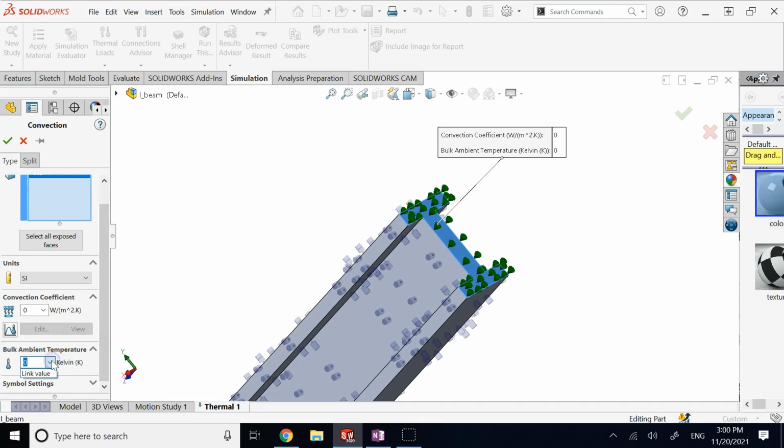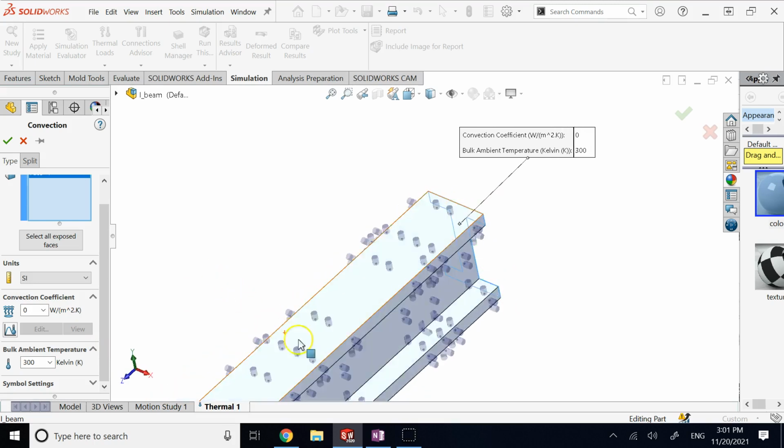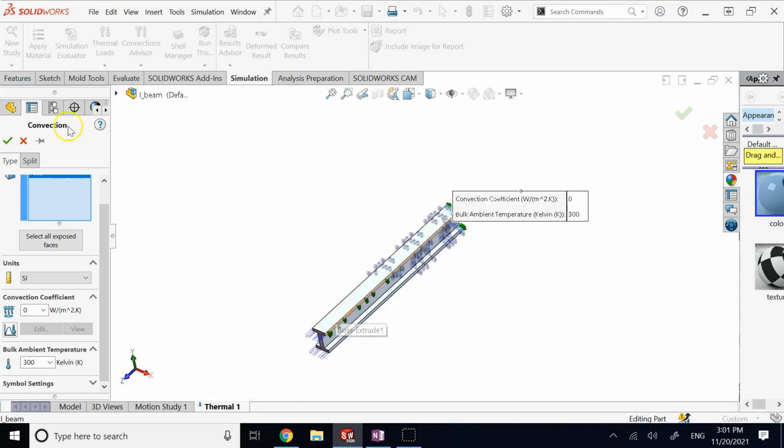And here, since it is in kelvins, I make sure it is less than 200 degrees Celsius that I had on the front end. So, I have to add 273 to Celsius to make it Kelvin. So if I say, let's say 27 Celsius, that's like 300 Kelvin, right? So I have to say 300. So I make it like 300. So it's kind of like normal temperature, right? Outside 27 degrees Celsius or 300 Kelvins. The other side is now way more than that.